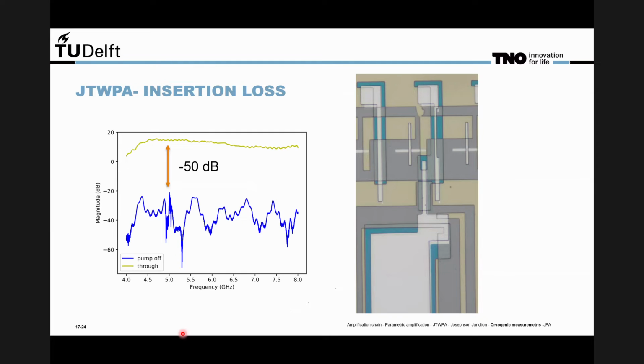After unloading the TWPA device, we found a small niobium titanium defect connecting the transmission line to the ground. The defect is here, shown in the red circle. This could be a weak superconducting link, which can easily switch to a resistive state, causing a lot of reflection in the signal.